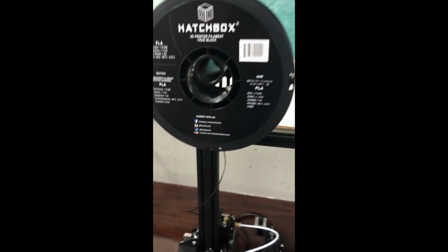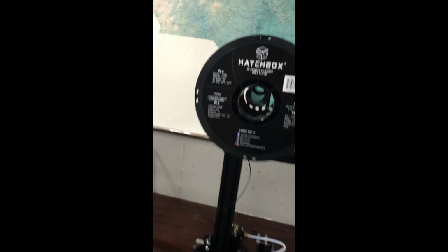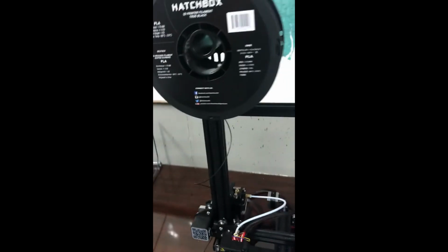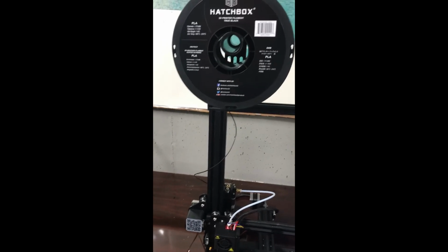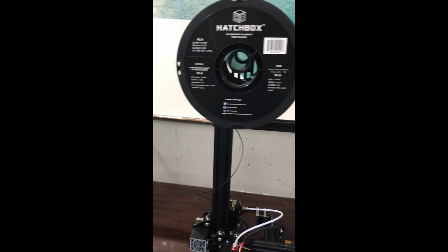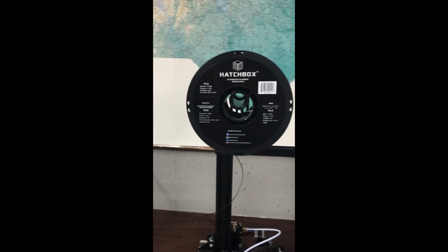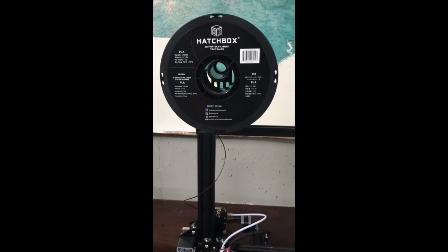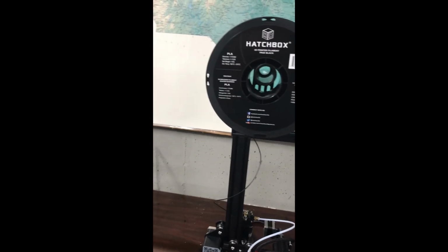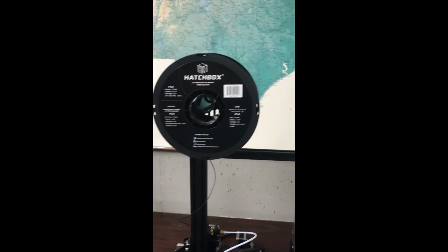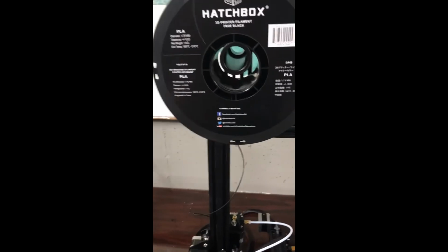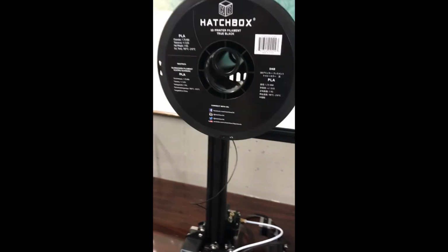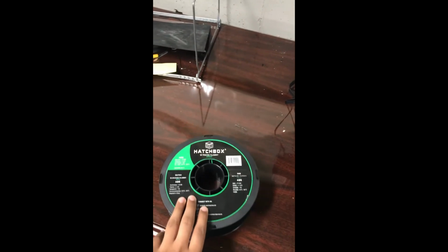Now, there's 2 main types of materials you can use in 3D printing. I'm using PLA plastic, but there's also another one called ABS plastic. Now, they both have their pros and cons. Pros of PLA: very easy to use, very easy to work with, doesn't need a lot of specific settings, and it's fairly cheap. The cons, though, is it's very brittle. It's not very structurally sound. I wouldn't recommend using this for parts for robotics or mechanics. And so it's not really a good option for robotics, but for my use it's perfect because I'm just doing a simple print.